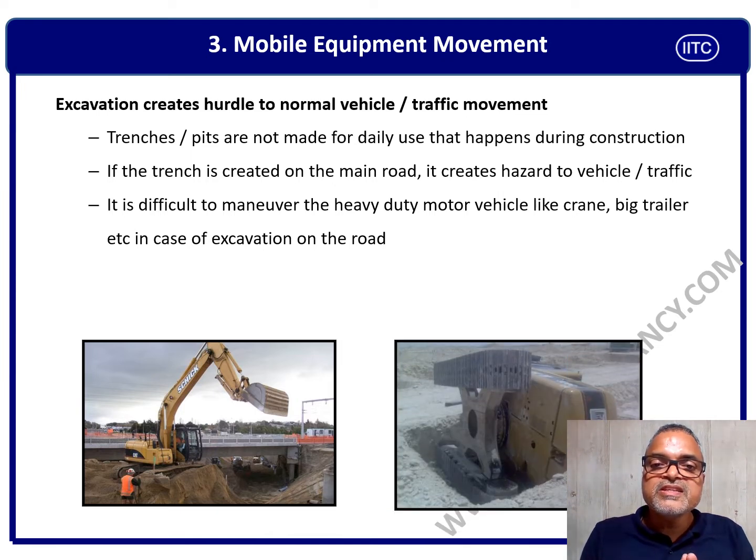If the trench is created near the main road, what will happen? This can create a problem for traffic movement or vehicular movement, and it is very difficult to move heavy vehicles like cranes and big trailers near the excavation area.